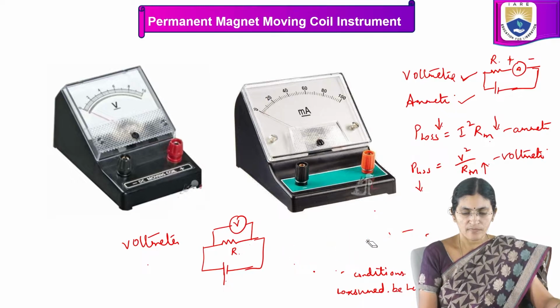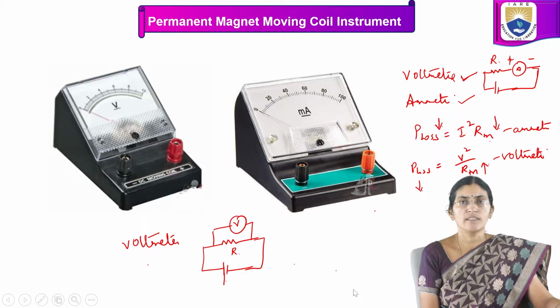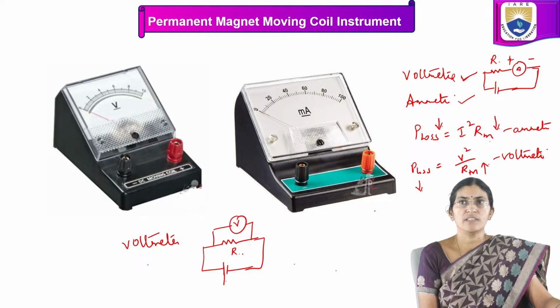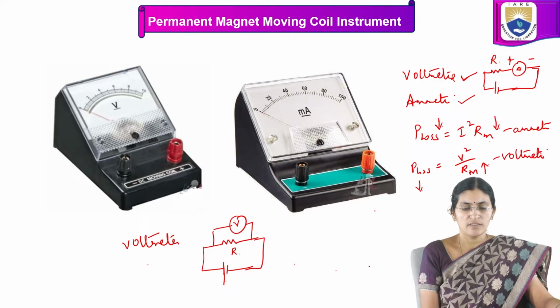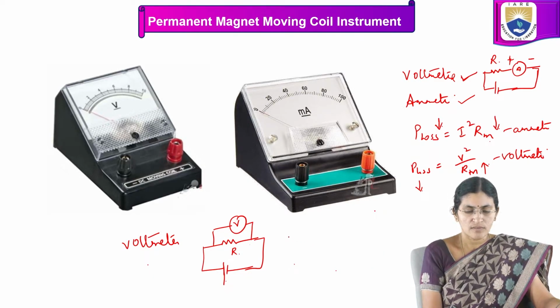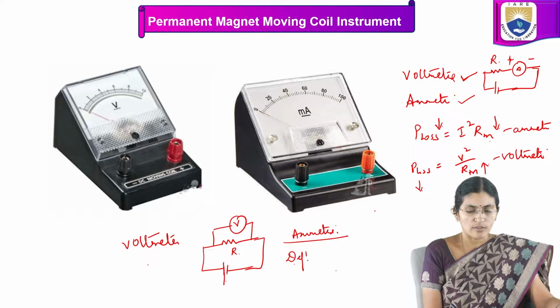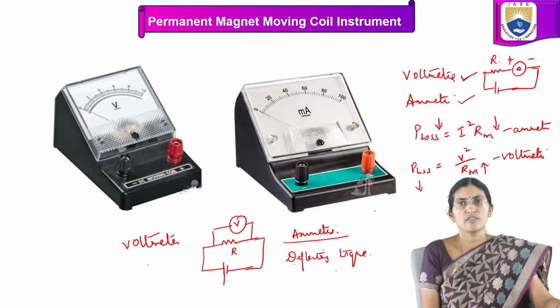These are some of the important characteristics of an instrument. In this class we will discuss analog voltmeters and ammeters. Analog voltmeters and ammeters depend upon electrical input and give mechanical output, which is the mechanical movement of the pointer. The mechanical movement of the pointer in case of an ammeter is due to the deflecting torque, which is proportional to the current to be measured.